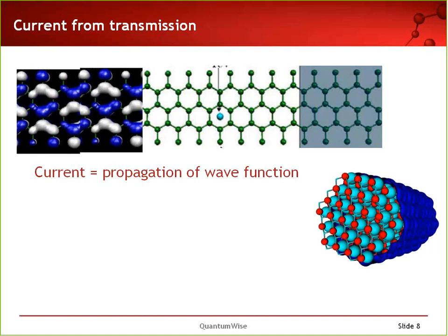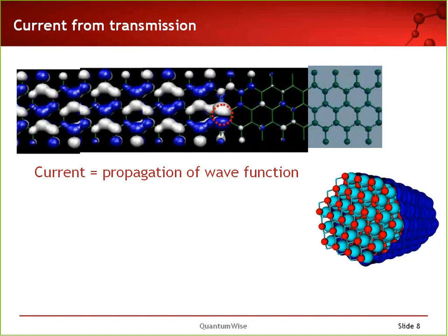So what happens to current when we go to the quantum level? If it's not described by Ohm's law, then what is it? Well, in a ballistic conductor, where as I mentioned the electrons are not really scattered, they don't have time to scatter during the time they travel from source to drain, if we take a transistor perspective, then instead current is in fact a propagation of the electron wave function. You have constructive interference, you have scattering events, still you have scattering, but it's some sort of potential scattering instead. So it's coherent and it's also elastic. So the electrons do not lose momentum and they do not lose energy as they traverse the gate region.